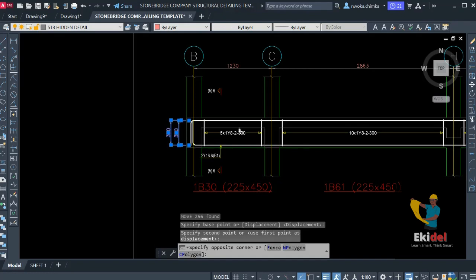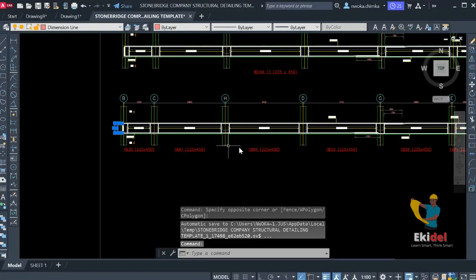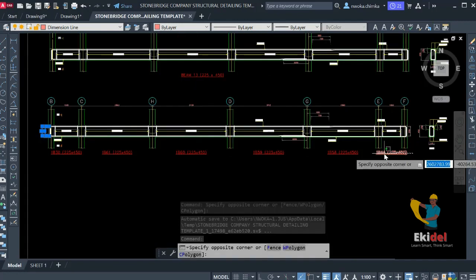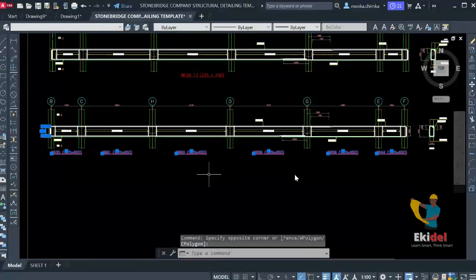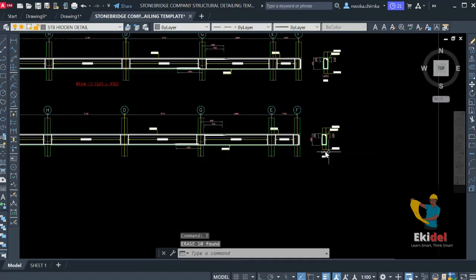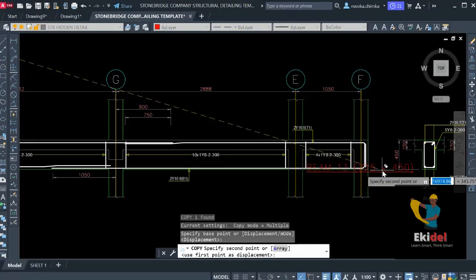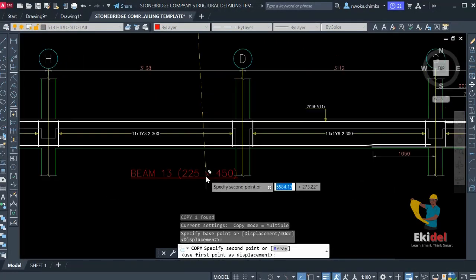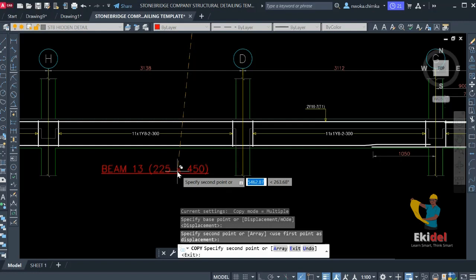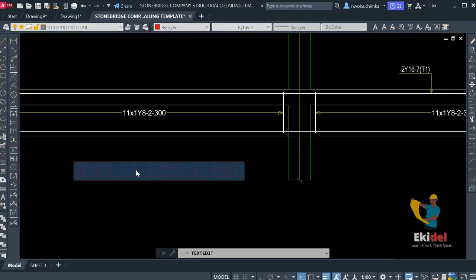Remove unnecessary things that came with this structure, this structural beam detail from Prota Structure, and remove this beam naming so that we can name it our own master beam name. Okay, so we just copy this right now to change this. The size is also the same, 450. Always check that so that you don't make a mistake to change the depth during your structural detailing.